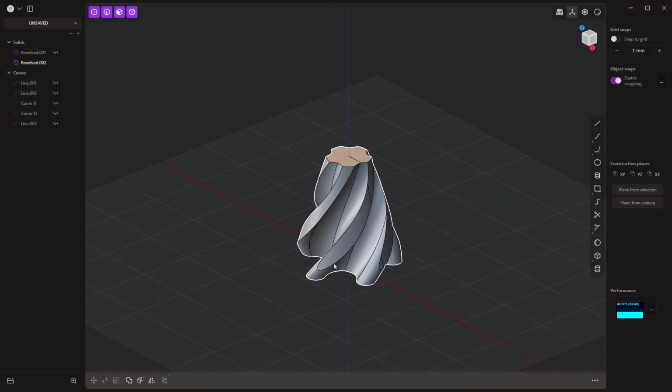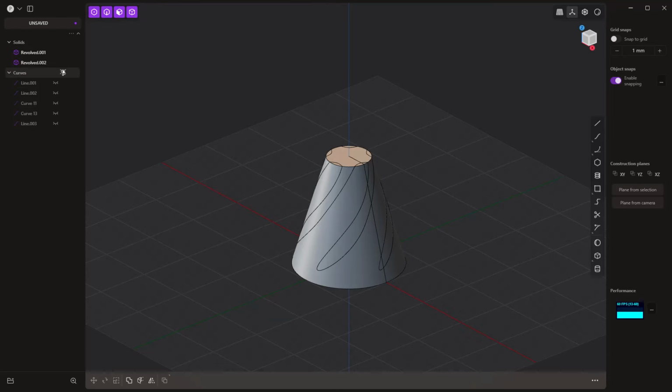Another quick note, if you make the angles steeper, so if we did a 360-degree revolution, for example, then you are going to have a harder time sliding these things together. And the main reason for that, again, comes down to the angle of those layer lines. The steeper that angle is, the less smooth your part is going to be. So it's going to have those problems. So now the issue that we have here is we need to create a gap.